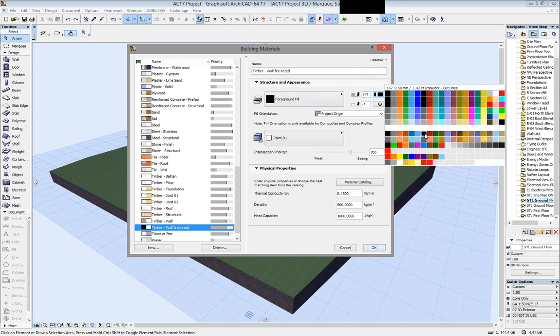And for all of them, you have a cut line, which is what's appearing on the outside in your plans and sections, and then your fill pane, depending on what fill you use. So if you're creating new building material, it is better if you stick to these panes. It'll just be a lot easier to manage with just 2 panes instead of 7. But Mark's going to go into the pane set at the end of this webinar and talk about how it's all formatted and get used to it.